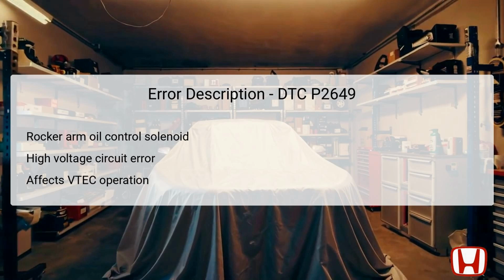DTC P2649 signals a high voltage condition in the rocker arm oil control solenoid circuit. The primary component affected is the rocker arm oil control solenoid, which regulates oil flow to the VTEC system. This solenoid is pivotal for adjusting valve timing and lift, directly impacting engine efficiency and performance.